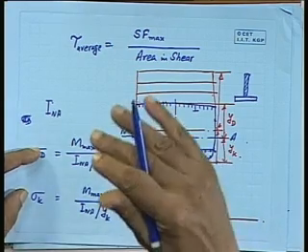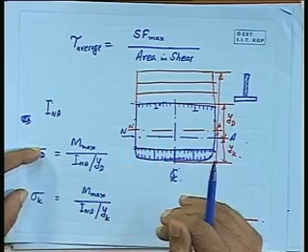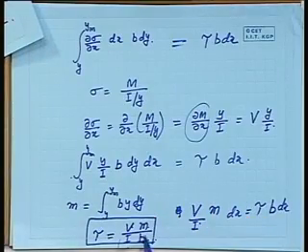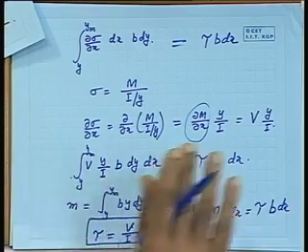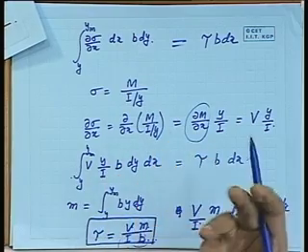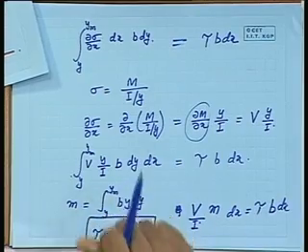So that means the horizontal member is not taking the shear force. This expression says that this becomes too much. As soon as this increases, this stress comes down drastically. The horizontal member does not contribute in taking the shear stress. Its contribution is negligible, whereas the vertical members take the maximum shear stress of the loading. That's what I told you earlier, and this expression also tells you the same thing.